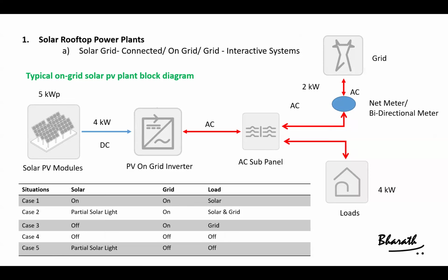So here the PV modules are what everyone is mostly setting up right now in the commercial market. The modules will generate DC and this is the inverter. It's a grid connect inverter. Whatever power comes in as DC, it will convert to AC, and it has a synchronizer in it, so it can sync with our existing grid frequency and voltages.